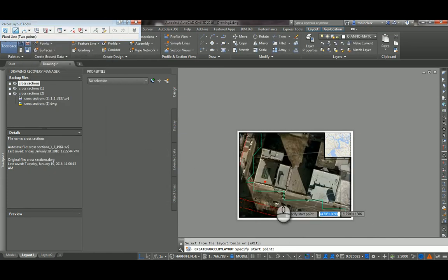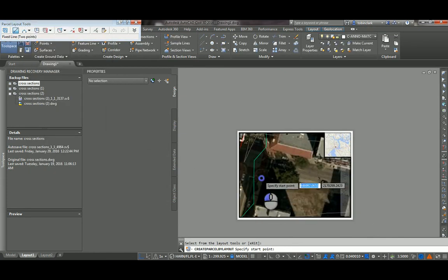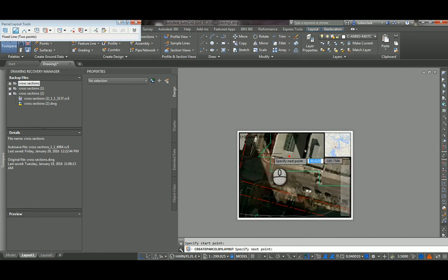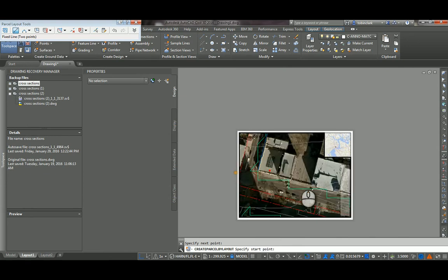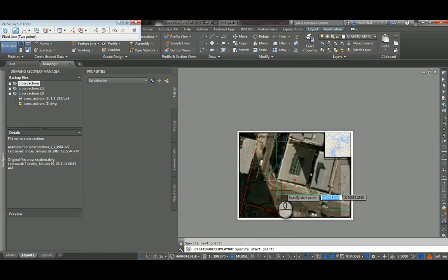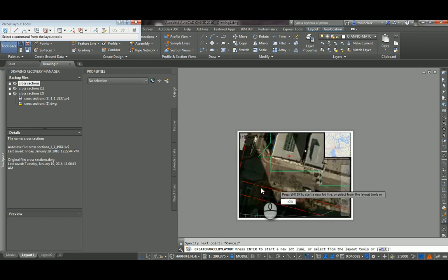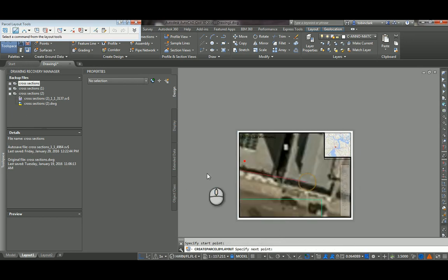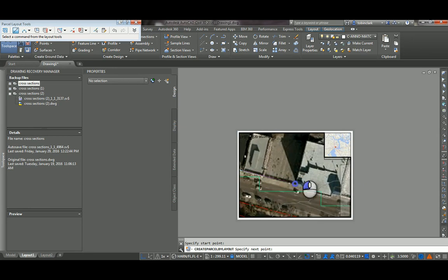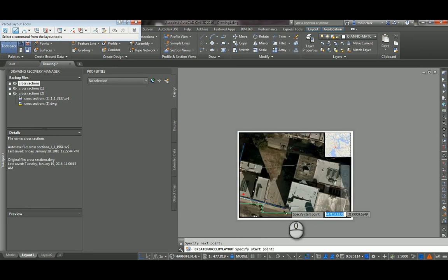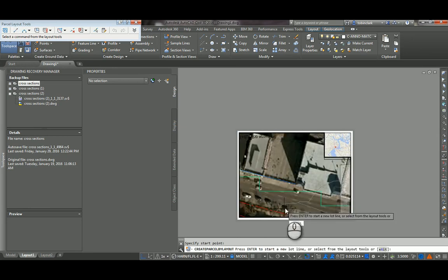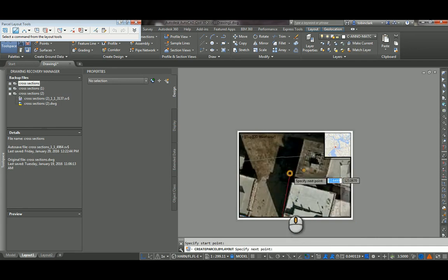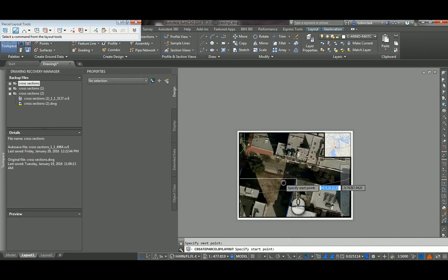Okay, so there's property 1. We can edit the label style, so it does that. And we can. I actually don't want that. I wanted to change this to area and perimeter, and I wanted to really quickly annotate it with the labels. So we go to parcel. Multiple segments, just like that. Dang it, because I did it like this.